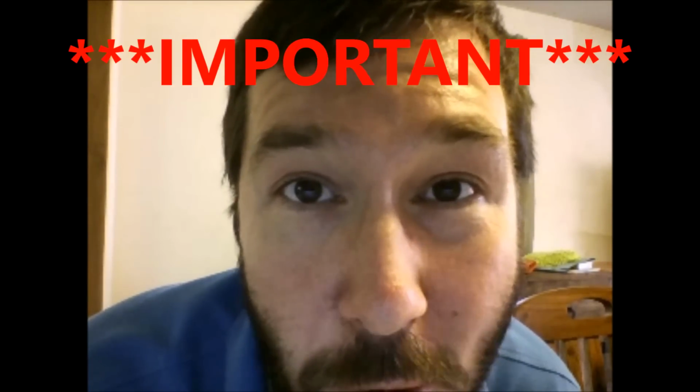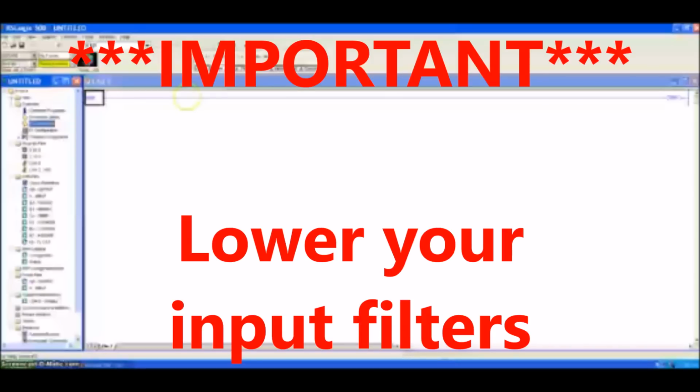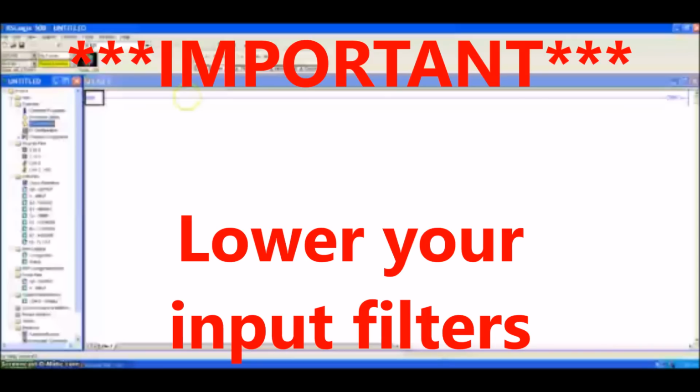So please, important, listen. Absolutely the most common mistake I find people have made with their high-speed counter configurations isn't actually in the configuration, which can make it impossible to stumble across. By default, the Micrologix 1400 input filters are set too high to detect a pulse off of an encoder. Pretty much they are set higher by default to give the controller greater noise immunity.